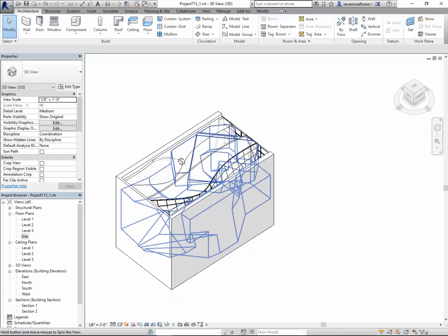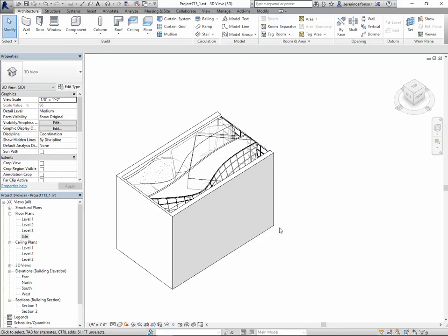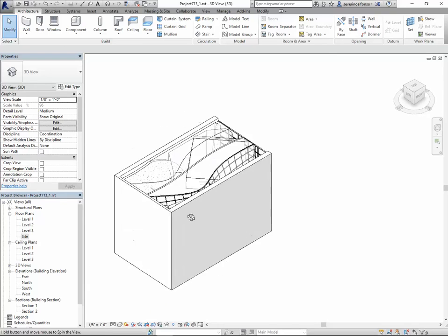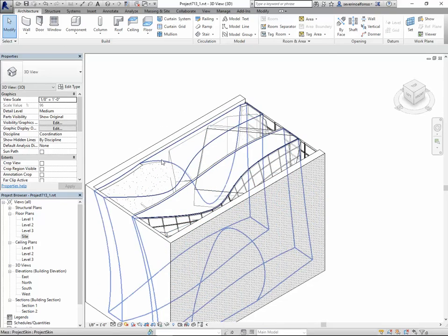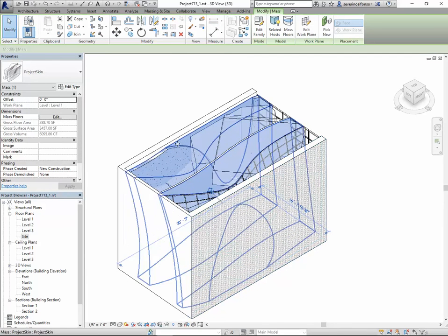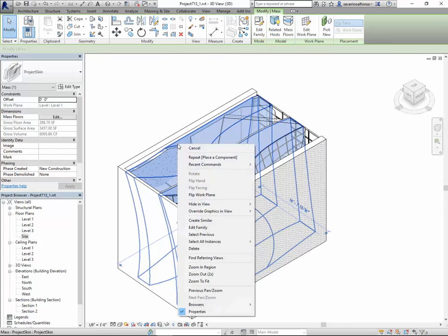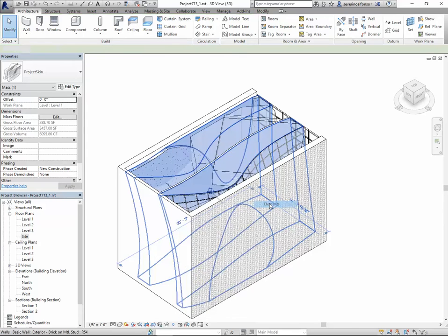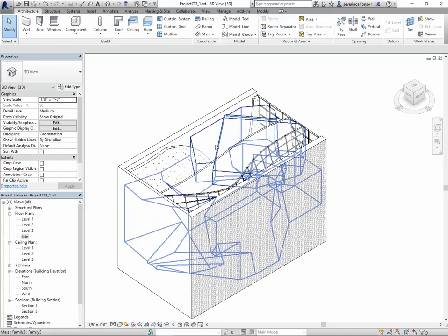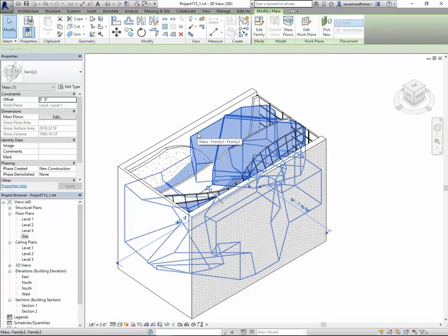So it starts becoming a bit tough to read so many conceptual masses at the same time. You're welcome to save and save as whatever other name and start eliminating some of your conceptual mass, or you just be good at right clicking and hide elements. So for whatever element you might want to consider just hiding.